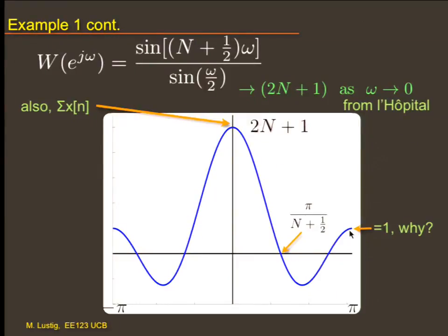And you sum over them. So you multiply plus minus 1 over your 1s. Now you sum plus minus 1s. Plus 1, cancel. Plus 1, cancel. Plus 1, negative 1, cancel. But it's an odd number, so you have to end with a 1. That's going to have implications when we talk about filters. Because if you have an odd number filter, you might end up with some value, and you're going to still pass some frequencies. There's not going to be a null at pi. It's going to be attenuated, but there's not going to be a null there. Remember that. Odd, even.